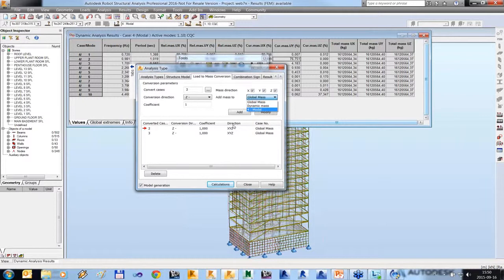And if you assign loads converted to a particular model case, you may create several different types of analysis with different parameters. So, for example, you may exclude a certain part of the model from mass, defining the self-weight on part of it. You may assign that to one model case and create another model case with the conversion of the entire self-weight, and compare the results and see what difference this makes to decide which option is better.